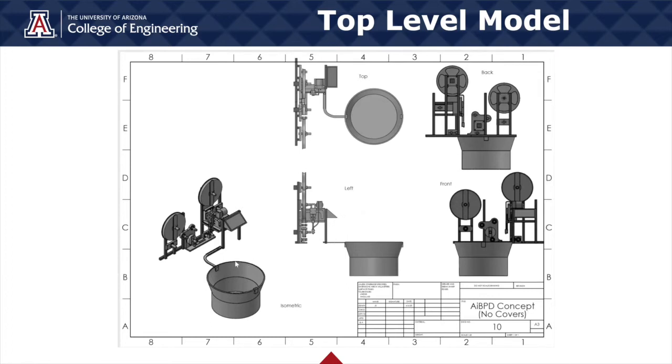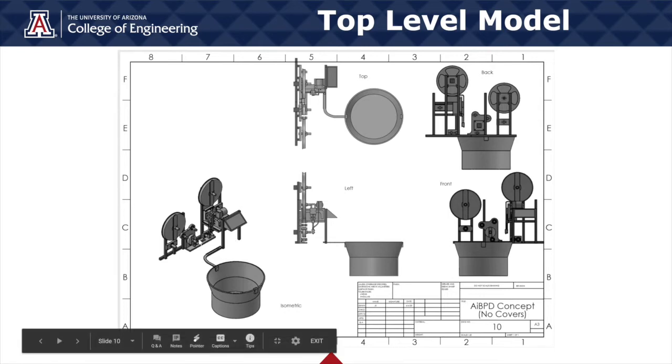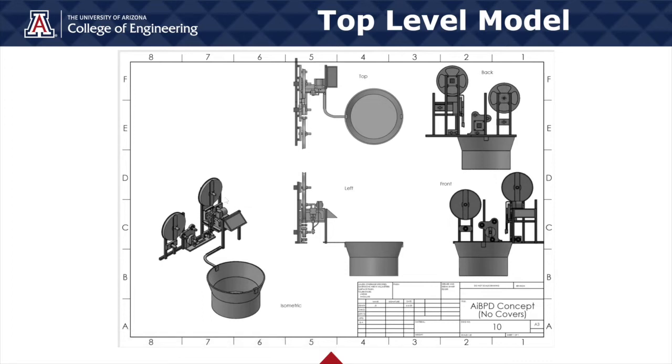The subsystems include the GUI, pick and place, FeederBowl, sticky pad feeder and clear cover removal, and the Reroll, which will be explained in detail individually in the following slides. Some engineering features are that the whole system uses the same ball bearings, the same sized axles, the same 20/20 adjustable frame, the same 4 varying length M3 screws, and the sticky pad feeder, Reroll, and free roller use some of the same parts. As seen in this system assembly, it shows how the subsystems are spaced and how the hardware works when put together.